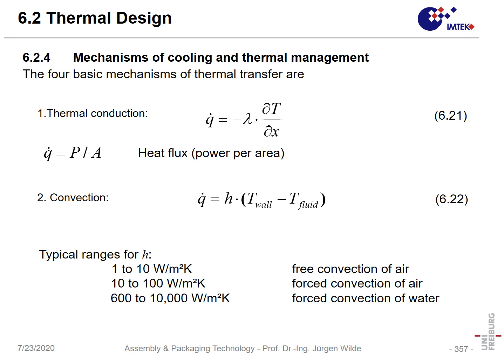Here we have the Fourier equation that says the power density or the heat flux, that is power per area, is proportional to the thermal conductivity of the medium in which we dissipate the heat and the gradient of temperature. Please note that the thermal conductivity can be temperature dependent, but in our lecture we assume it to be constant over temperature.